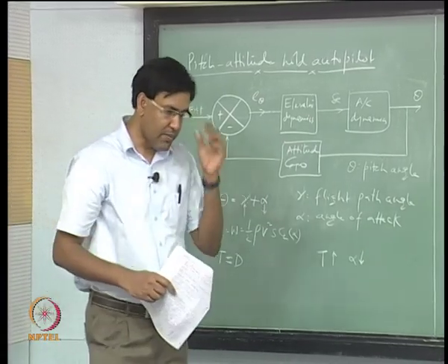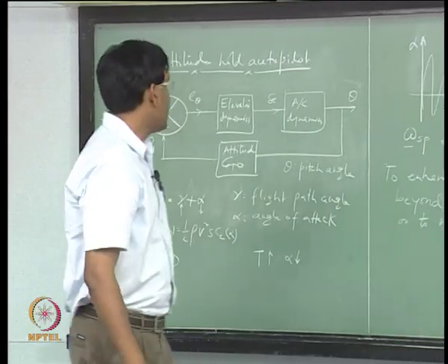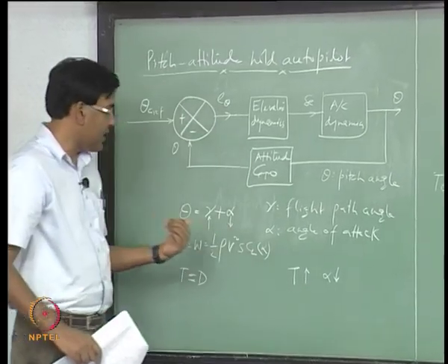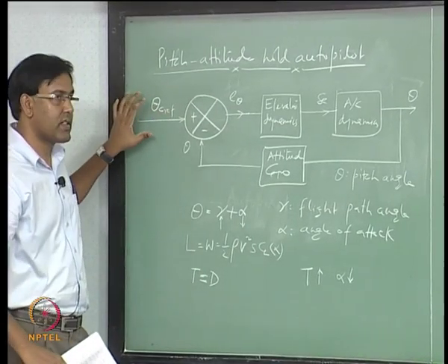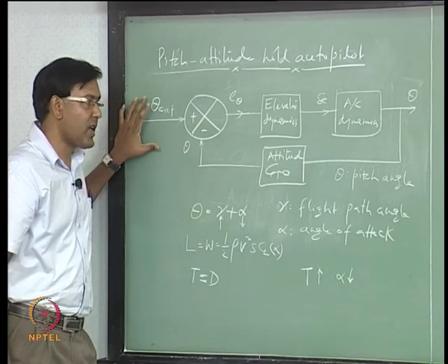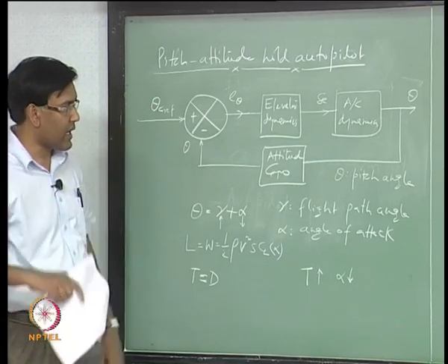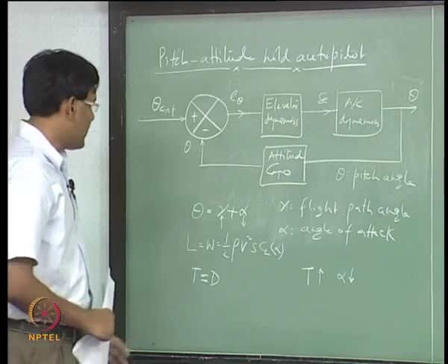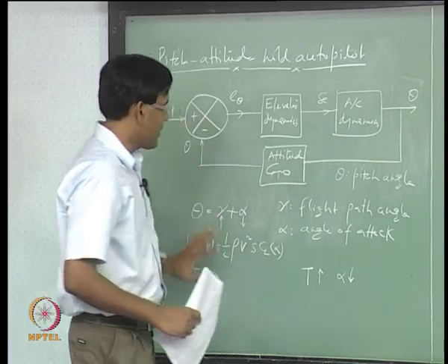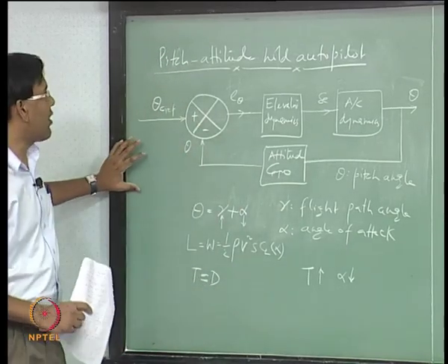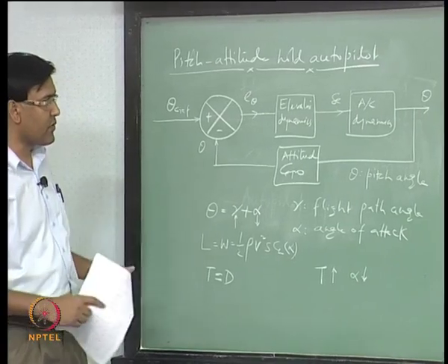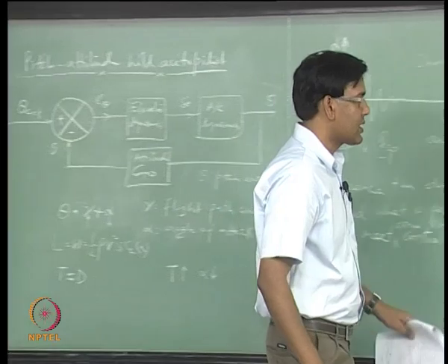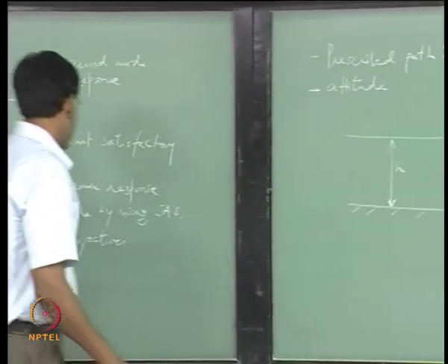Even when we are flying a climb flight, it may so happen that finally, if we are just using this controller autopilot, finally the aircraft may just level out. So, this is not a very popular autopilot, but is used within another autopilot, for example, this altitude hold autopilot.